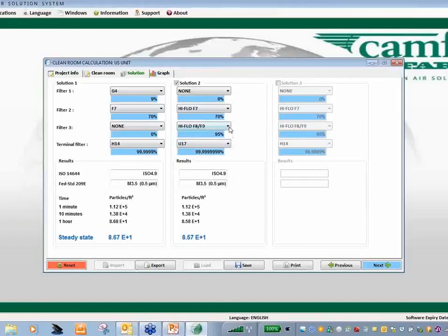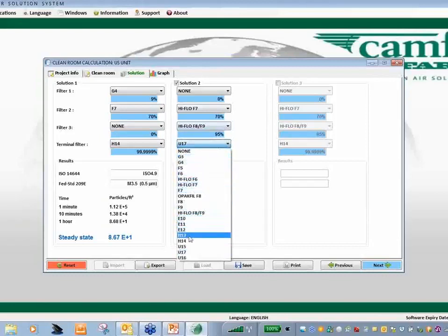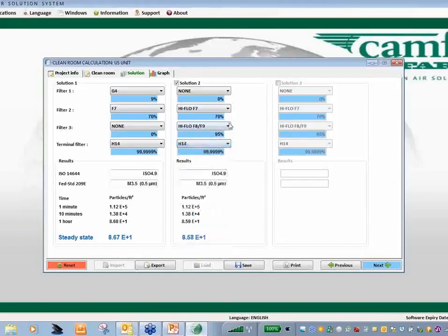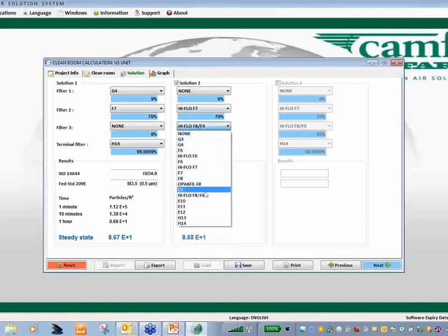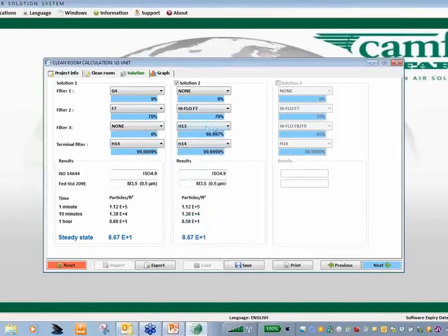One of the examples I talked about this morning, we had another one of these webinars at 9 this morning. I know in Puerto Rico on an application, a particular end user had 3 steps of filters. In fact, 4 steps, but they had HEPA here in the makeup air. We looked at whether there was really a need for that HEPA filter before the HEPA, so we said we'd look at downgrading to E10 or 95% DOP to take advantage of the energy savings.